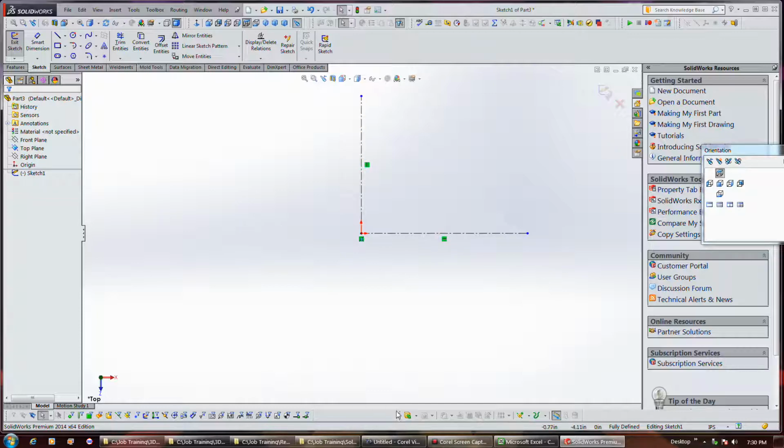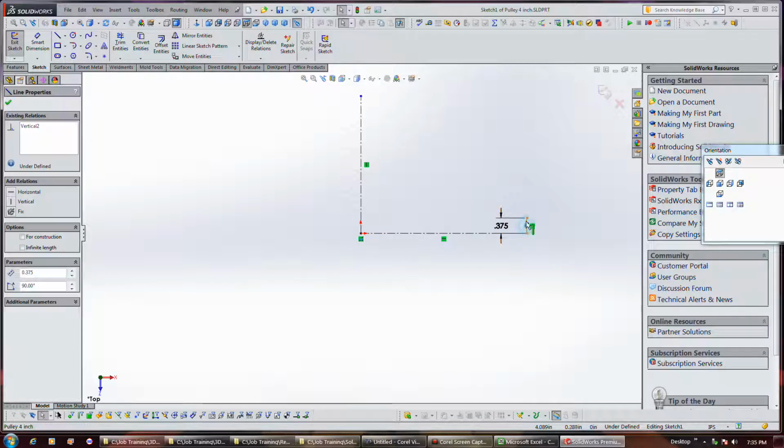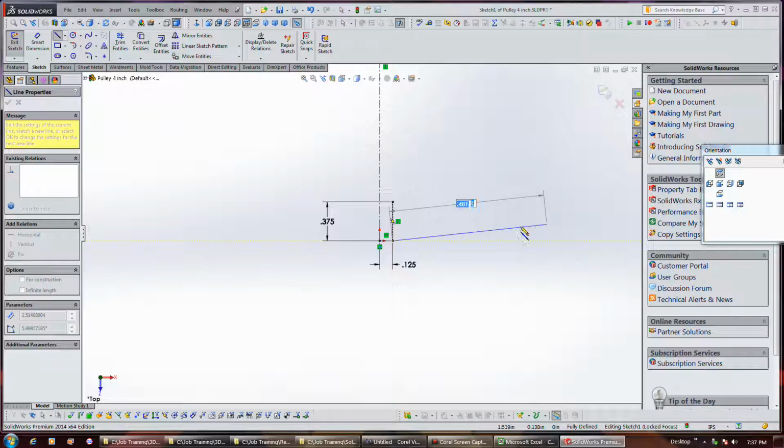Now, you'll notice where the bar is right now, it's below the sketch. I assume it has to do with it being underdefined. Now this construction line has a horizontal constraint, so that means our line really can't move up. It can move left to right, but it can't move up. Okay, now I've started another line from that point. Now, you'll see the inferencing line pop up. You'll see to the right of the pencil there's a little white inferencing indicator.